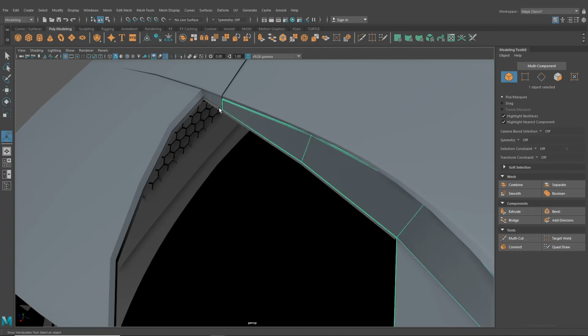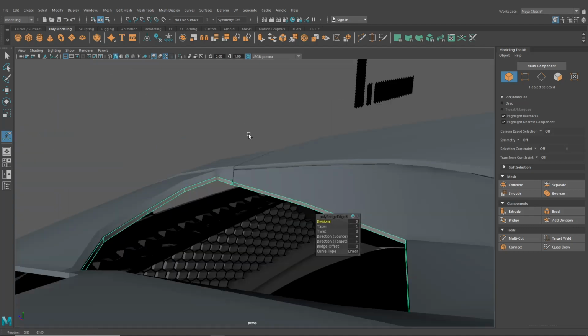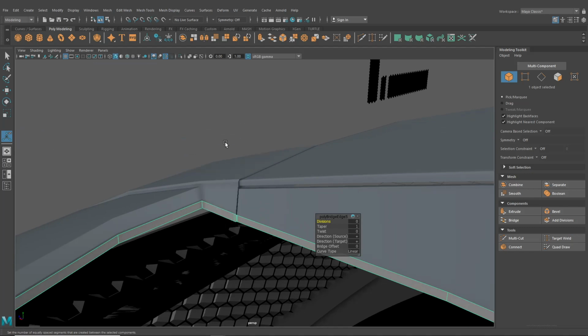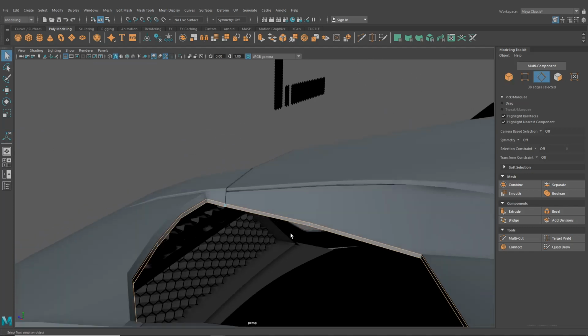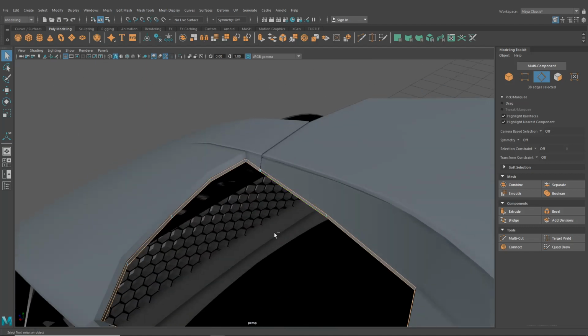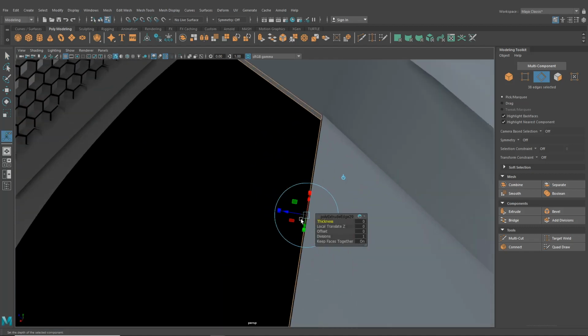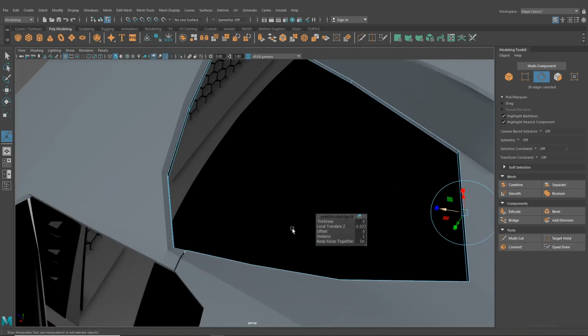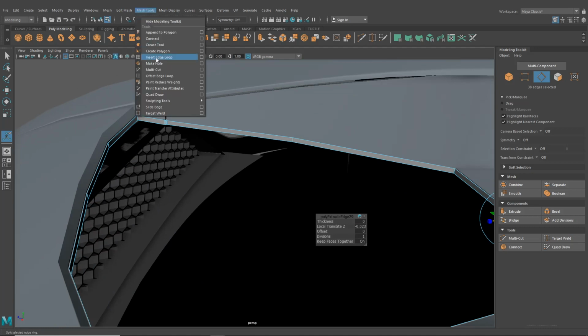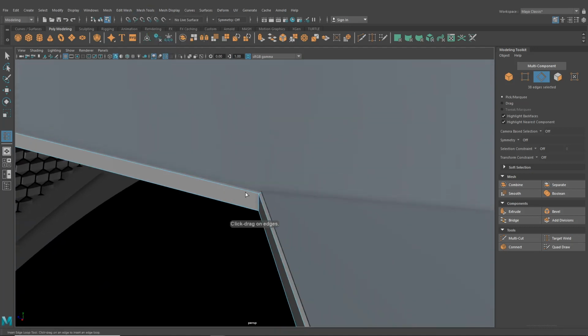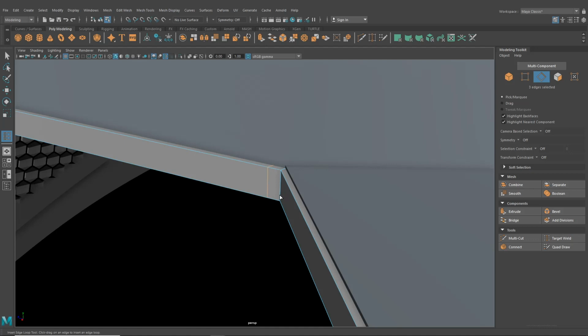I'm going to attempt to select that. There we go. I'm going to go around, I'm going to double click top and bottom, I'm going to hit Control E, I'm going to push out on the blue there. What that should do is that should make that nice and thick to go inside. And I'm going to insert some edge loops, so I'm going to go on the bottom towards the top, and then just that top bit there.